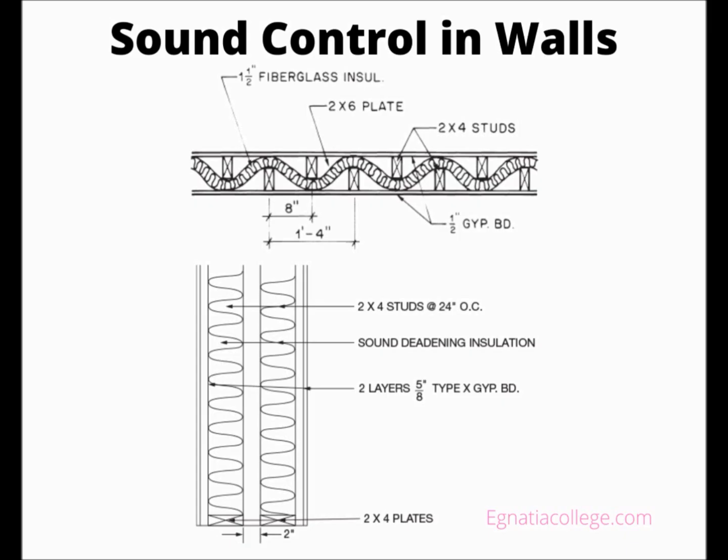Sound can bend around corners and find its way through the smallest of openings. The air carries the sound to the other side of the wall, where it is transmitted to the air on the opposite side of the wall. The drywall joint between the wall and the ceiling may require sound deadening putty to prevent sound from passing through that joint. The electrical installer may be required to utilize acoustical insulation or some other sound attenuation material around flush device boxes.